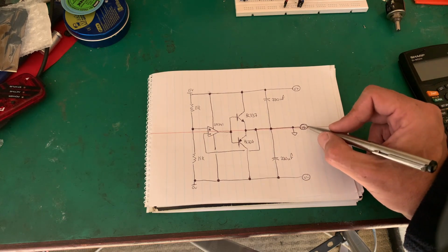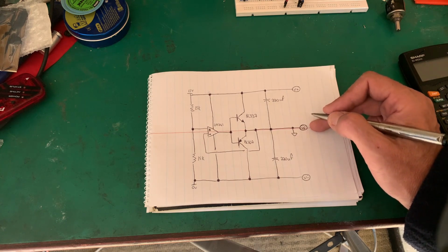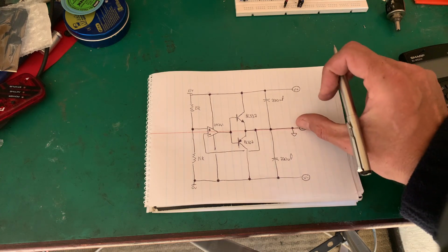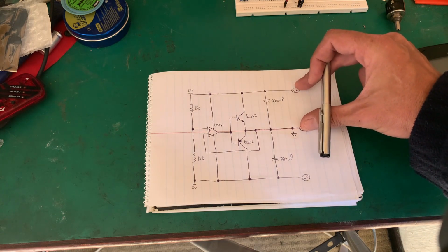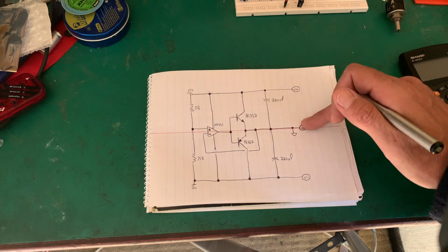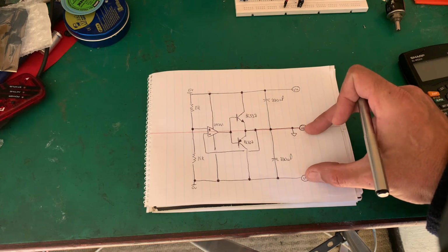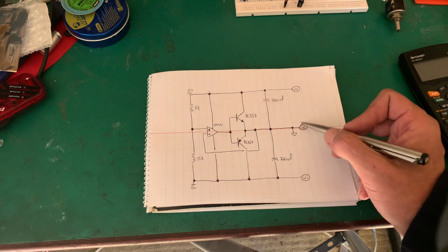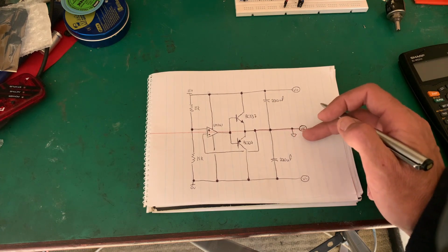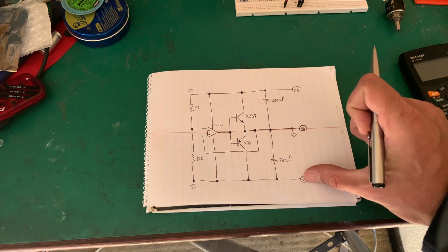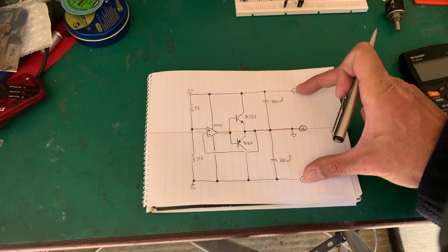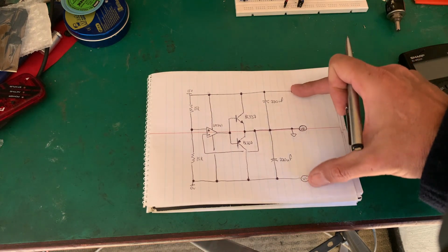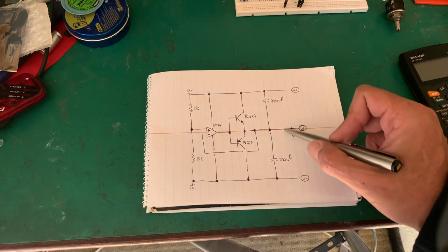In other words, we will use this point from now on to measure as our reference point, our common on the multimeter. So the black lead will go here. If I measure from here to here, I will have plus 7.5 volts. If I measure from here with the black lead here to here, I will have minus 7.5 volts. So I've created a split rail, as long as I remember that this is what I'm now using as my reference point. If I put the black lead here and measure here with the red lead, I will measure plus 15. If I swap it, I will measure minus 15. So what we've created here is a split rail.